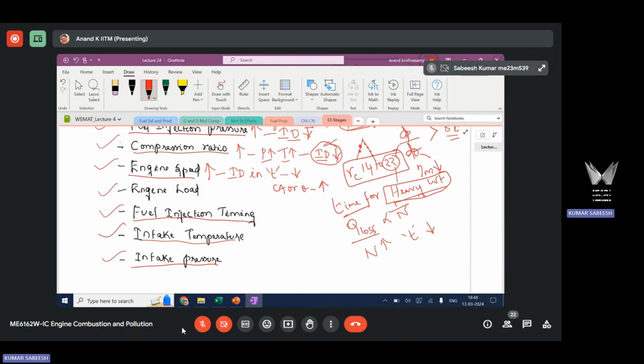The higher the engine speed, the shorter the overall cycle time itself. The combustion event consumes only a fraction of the overall engine cycle time, a very, very small fraction. When you run the engine at a higher RPM, the time of one engine operating cycle itself will come down, and the combustion event occupies only a fraction of it. So the time available for heat loss is going to come down considerably at higher RPM. Because of less time for heat loss, you are retaining more heat in the engine cylinder. When you retain more heat in the engine cylinder, how does it affect the delay time?